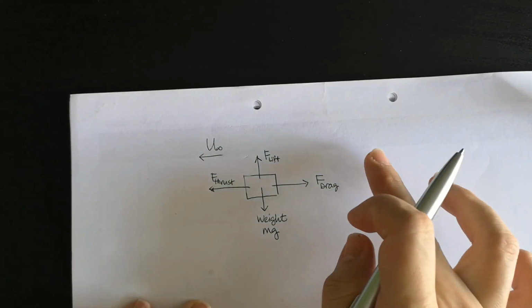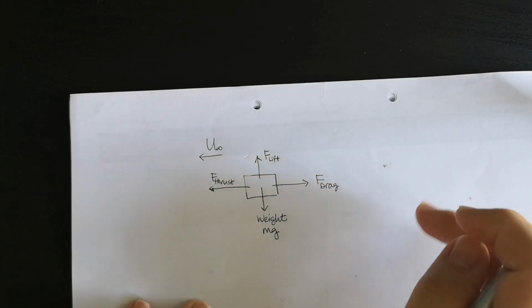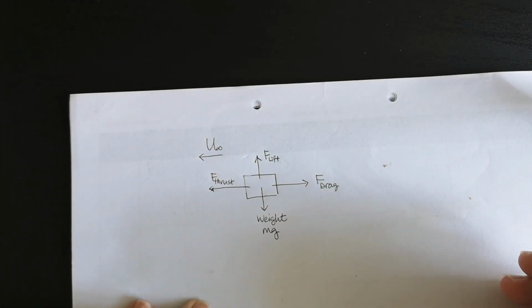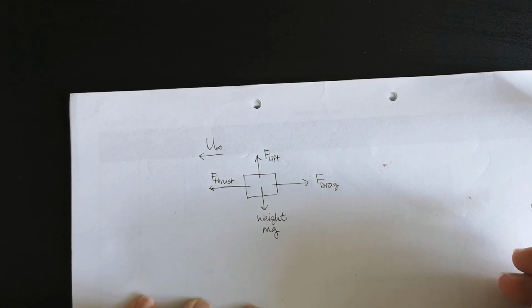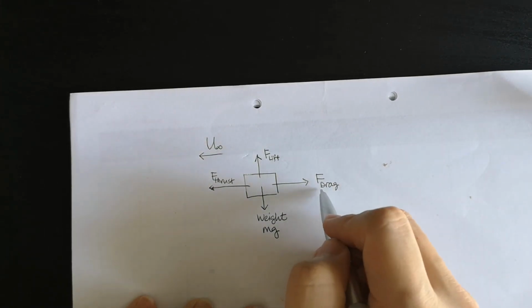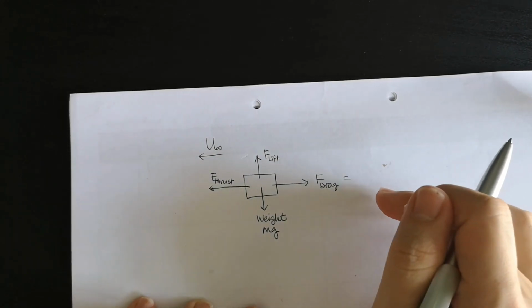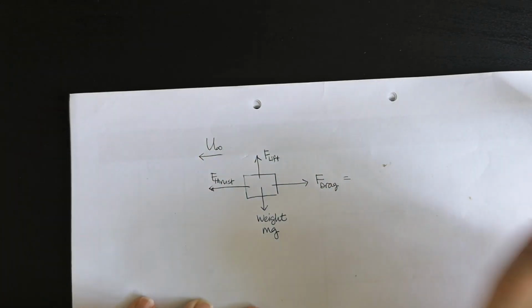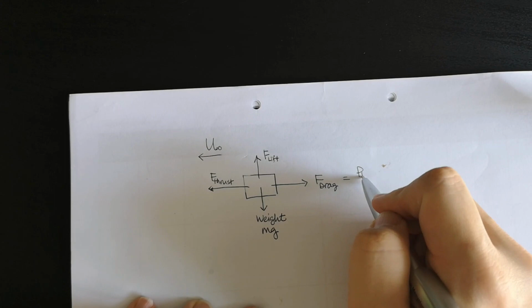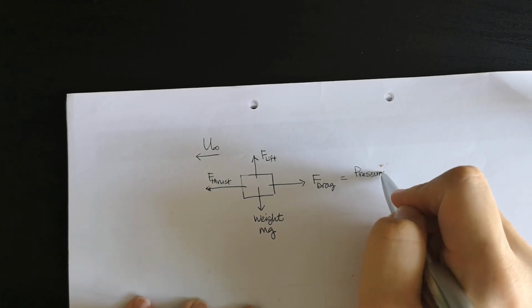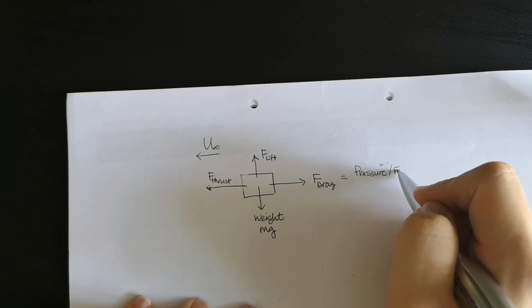Okay, so if you refer to the objective for the second experiment, flow over immersed body, we are to measure the drag force on an aerofoil and also to determine the drag coefficient for this aerofoil. Drag force, as mentioned, is a resistance. It is exactly the summation of different forms of resistance. First of all, we have pressure drag, or some reference books call it form drag.